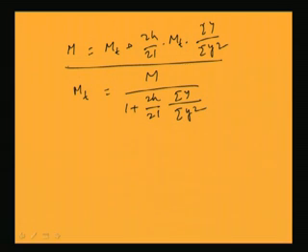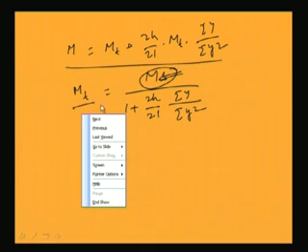So, what we are seeing here is that MT is nothing but the moment due to the tensile forces coming into the rivets, and M is the moment resisted by the entire rivet group, or the moment coming from the external. So, the external moment which is applied can be used for calculation of the total moment coming to the rivet groups in tension.